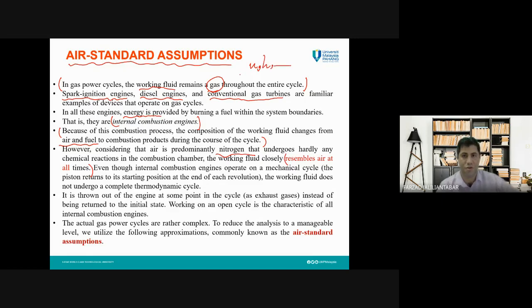As you know, we have different methods to find enthalpy and entropy for a cycle. How we can find that for a state, especially, we need to go to the tables. But we don't have those tables for all of the substances, or sometimes we need to use some complex equation to calculate U and H. But if we assume we have air as an ideal gas, then simply we can refer to the table for air as an ideal gas and find U, H, and then substitute in our equation. Then we can calculate, for example, the thermal efficiency of the cycle.